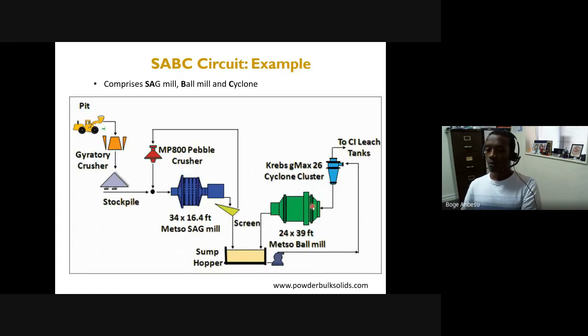Again, in this course, what are we trying to do? We're trying to achieve, or at least have an understanding of, what is involved in a typical comminution circuit. So we know primary crushing, typically we'll have another stage of grinding, and screens are typically used after either crushing or a primary grinding operation. And if it's a SAG mill, typically a SAG mill is operated with a recycle crusher. Okay, so I talked about why we use recycle crushers in one of the lectures. So have a look at those in the grinding section.